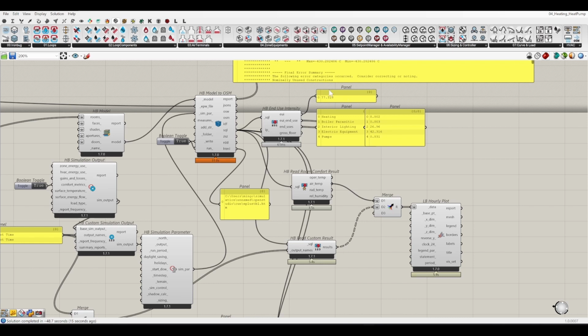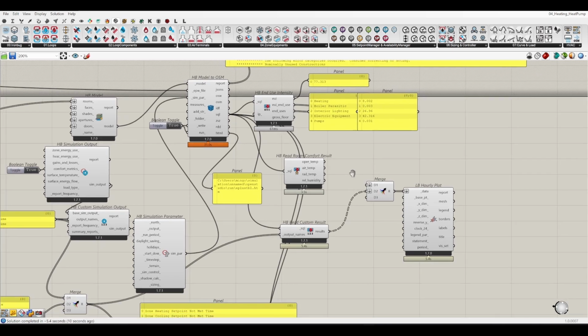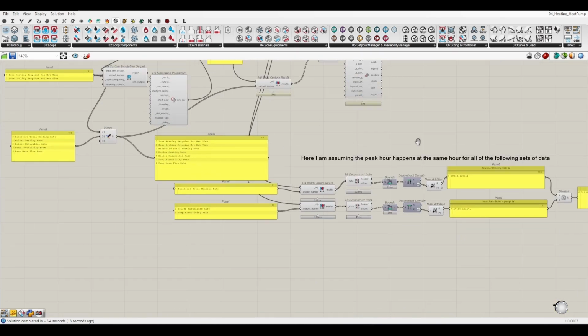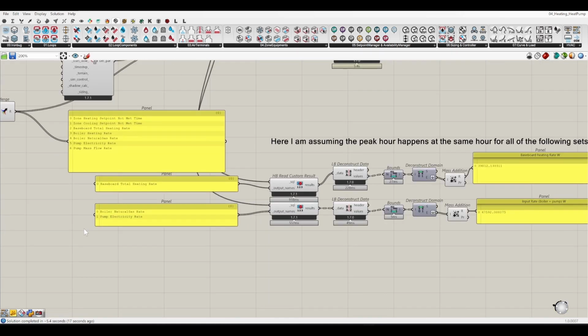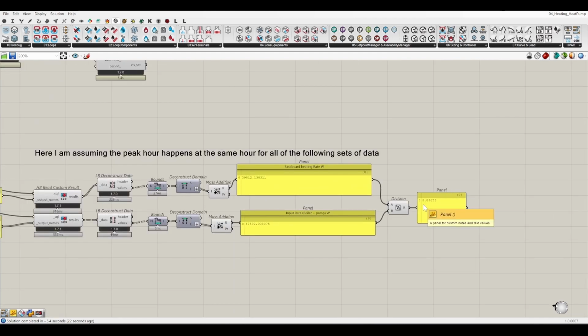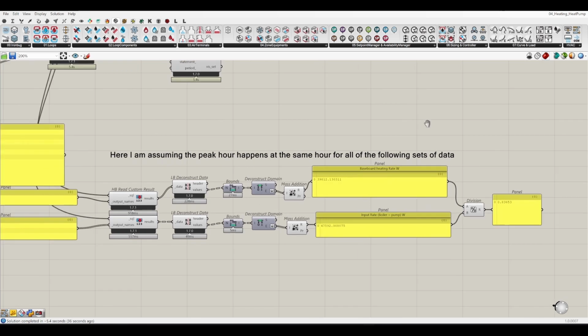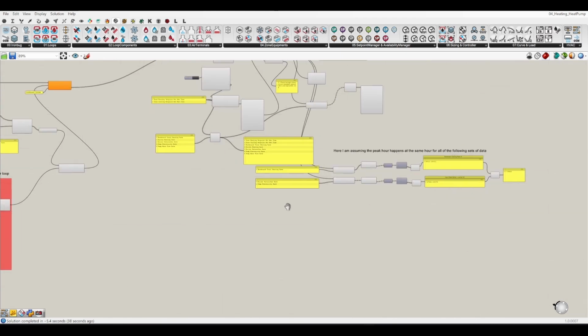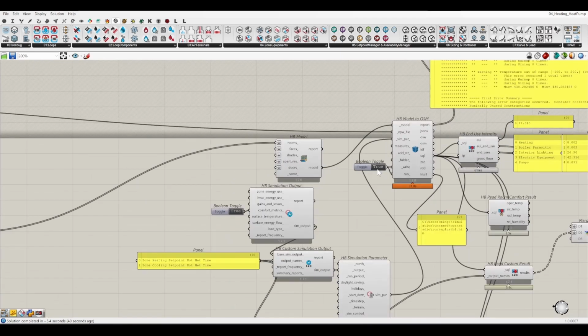So the total EUI is 77 right now, and heating is 8. Okay, and yes, we have calculated the total system efficiency. It's because we are using the condensing boiler right now. The efficiency is pretty high than the regular traditional boiler. Right now it is 83%.